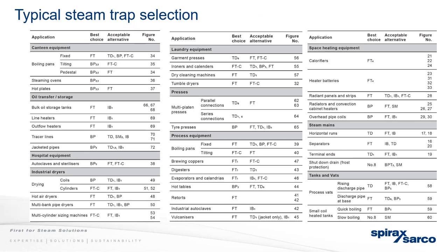So from a cost benefit ratio point of view, the small globe valves or gate valves or whatever become a lot more cost effective then, because you'll be continually replacing that ball valve. So yeah, it depends. Look at the application, look at the temperature, look at the pressure rating of the valve, and what's cost effective. A ball valve, for instance, and gate valves as well, use more material than BSA valves, bellows seal valves, so they are more expensive.